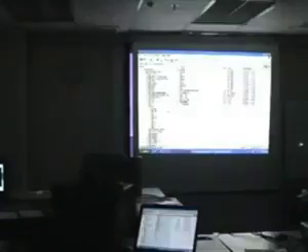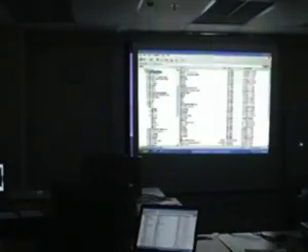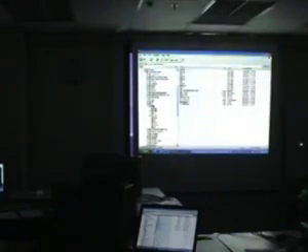Like if you go into Land Desktop, say for example, this is my land projects. These are all my different projects inside, which have been created using Land Desktop. Like in this particular project, these are all the different files and folders that have been created using Land Desktop. This entire folder indicates the project database. So when you want to back up your project, you want to back up everything inside here.